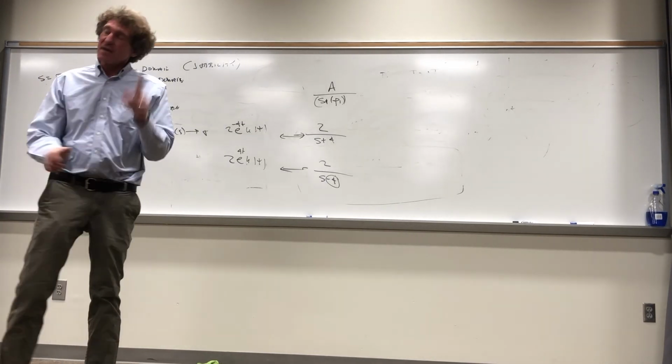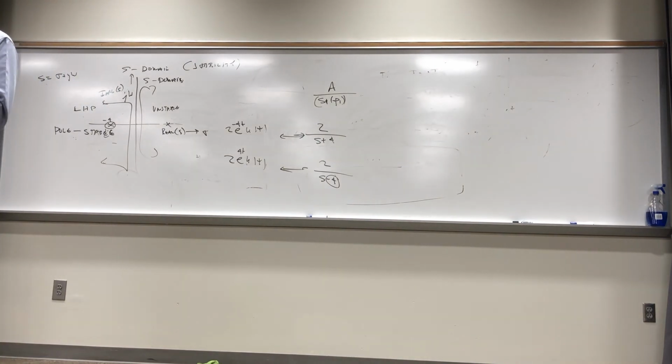So what Bose did is said, being an electrical engineer, I can do one better. He got a bunch of cheap speakers. And he looked at the power output versus frequency. You would like it flat, right? For any frequency, if you have 1 watt of power, you'd like the same amount of volume, decibels, coming out. That would be a flat response. And you'd like it clear. But what he got was, they do all sorts of things. So Bose took that frequency response and did the inverse of that, and he created an amplifier which has exactly the opposite or inverse properties as the speaker's response.